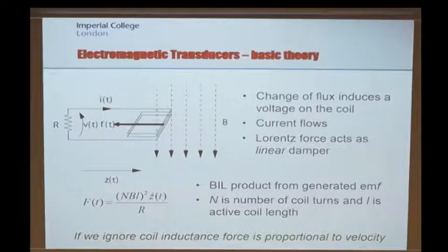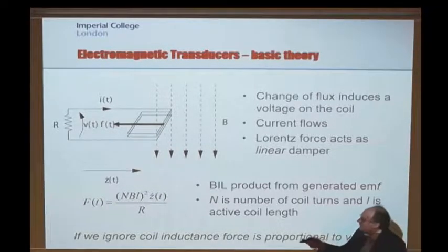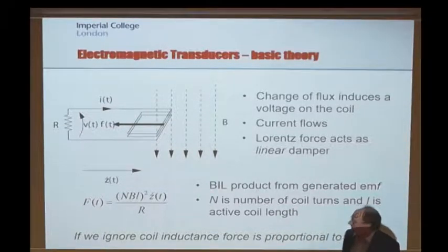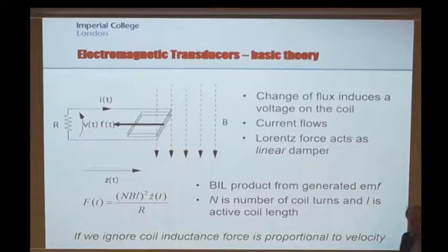So that's probably the first time that I've talked about control of the harvester. What we're trying to do ultimately here, as I keep saying, is to maximize the power density that we can achieve in these devices. And that is going to involve setting an optimal damping force, and setting an optimal damping force in this case means ultimately what can you change here in this device in order to change the damping force. The resistor is probably the obvious thing that you would want to be able to change, not implemented as a resistor, as I said, but implemented as a battery, and ultimately then a circuit which interfaces between the harvester and the battery. And it's that circuit then that we would control in order to change the effective resistance and change the damping that the harvester is seeing, and therefore constantly tracking the maximum power that we can extract from this simple mass in a box.